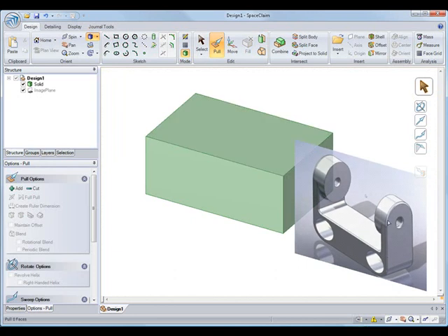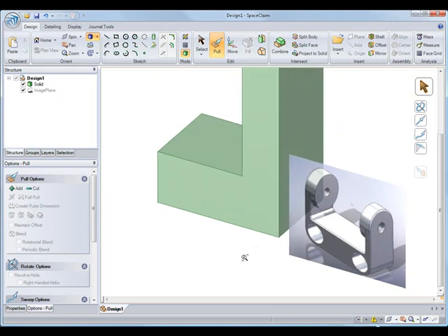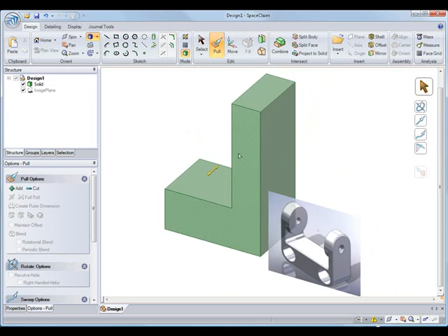So I've made our base block, but now I want to make the extended region on the right side of the picture. And to do that, I'm going to select the edge and extend it. Normally that creates a surface if I extend it one way or the next, but if I hold down Control, it actually copies that line, just like if I move and hold Control, it'll copy a face or copy a hole to a different location.